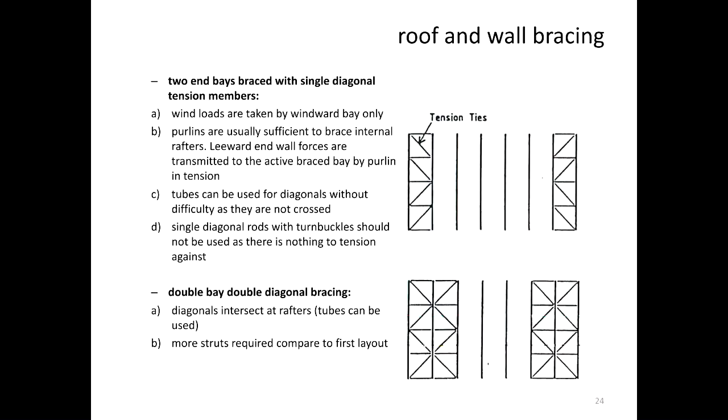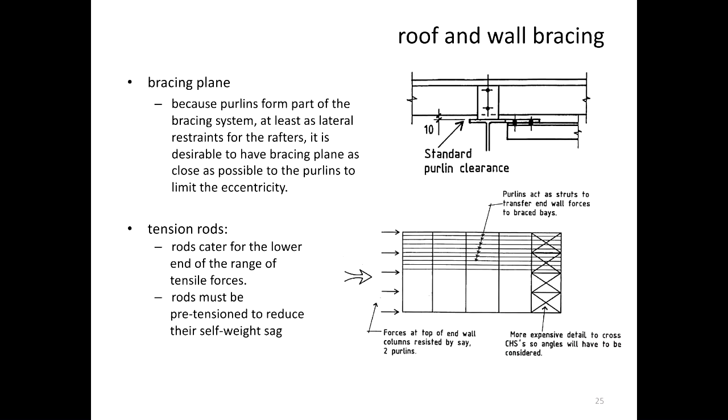Most times we use equal angles to do the bracing. Sometimes we use the round circular rod to do the bracing. So that all depends on what the engineer has designed. The rest there you can easily read. Okay? And that's similar to what I've just explained. What I want to bring to your attention here when you build the structures is looking at where the bracing sits at the